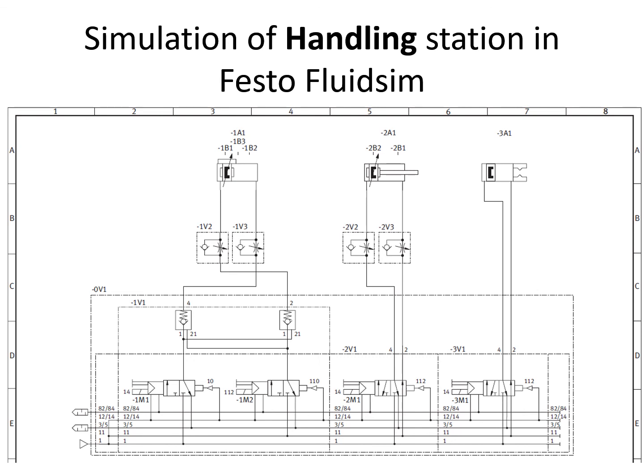plus we have these pilot non-return valves, and we have a bunch of 3x2 or 5x2 directional valves, and we have solenoids 1M1, 1M2, 2M1, and 3M1. This one, you see that we have a group valve. These are the internal components and valves of that group valve.